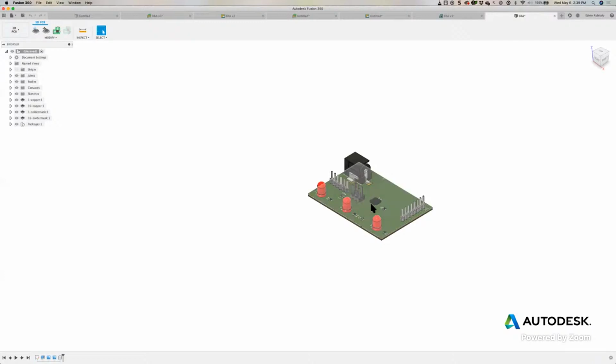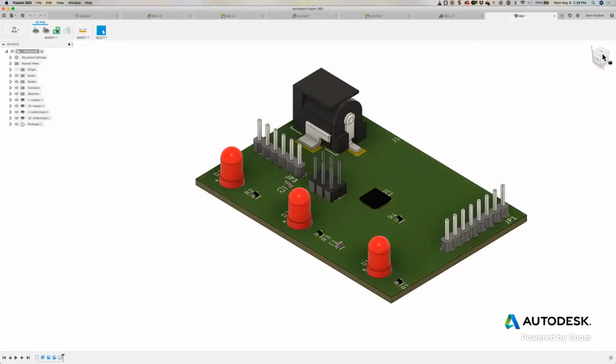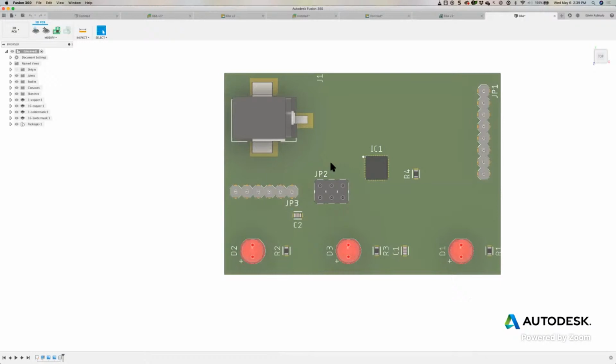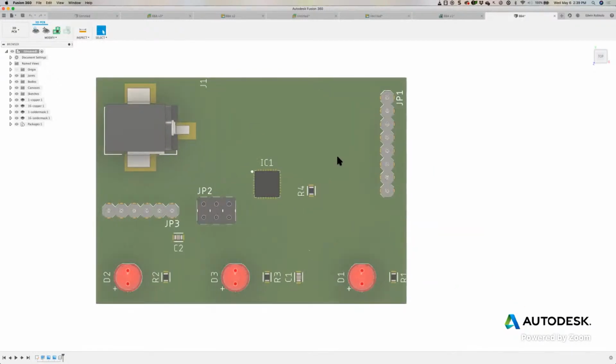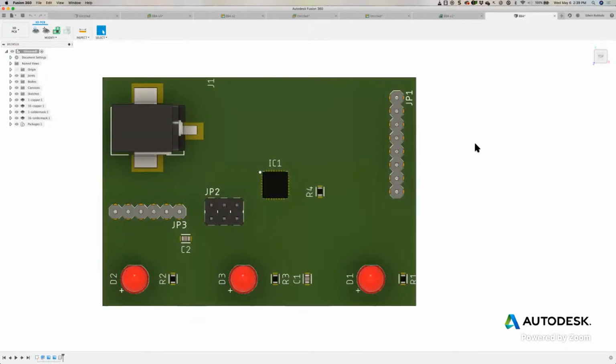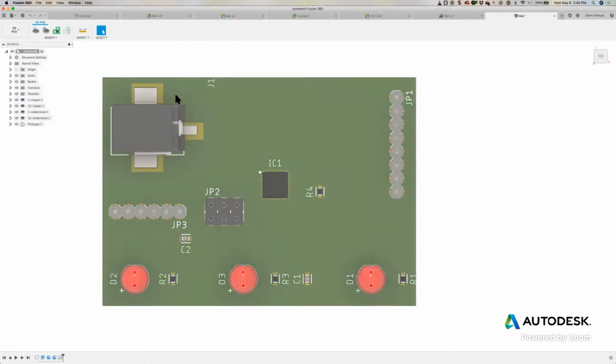And that's what my board actually kind of looks like in the 3D PCB realm, as we could see it. Now I could actually make some changes here if I needed to. I don't have any routing, so I'm not putting at risk any shorts or anything like that, even though we are going to do a small demo on how I can make changes, even though my lines are routed. But I'm going to take this jack, and I actually want it on the other side of the board.